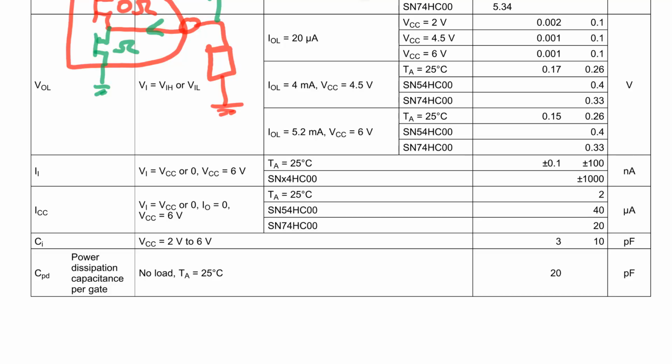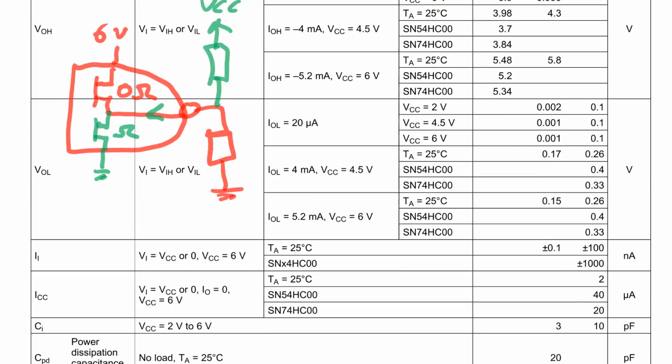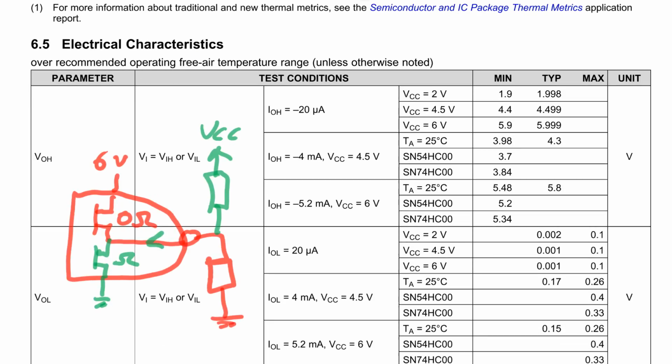You can do simple Ohm's law to figure out what the effective input resistance is at that particular voltage, but it's basically bugger all. But once again, that's going to change with temperature. So if you're relying upon that for some super duper ultra whiz bang low power design, that could matter. Watch out for it, and you could come a gutser there.